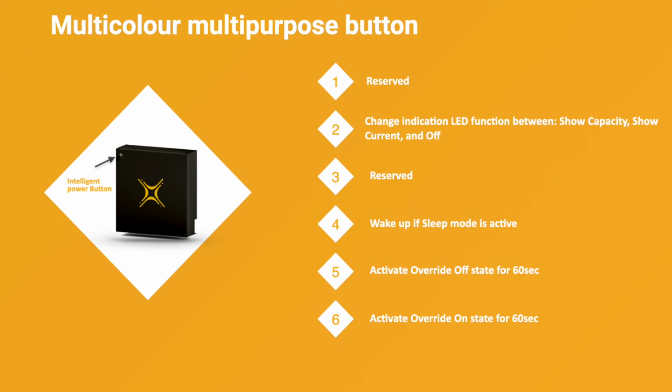The Intelligent Power button will also indicate warnings by the power button flashing orange, and it will indicate errors by flashing red. The Solar MD Intelligent Power button offers extended battery functionality. You can access these functions by opening the battery so that the BMS is visible and holding the power button in. This will take you through the menu, each of the 6 LEDs representing the following functions. To select an option, simply release the button and give it a single press to select.